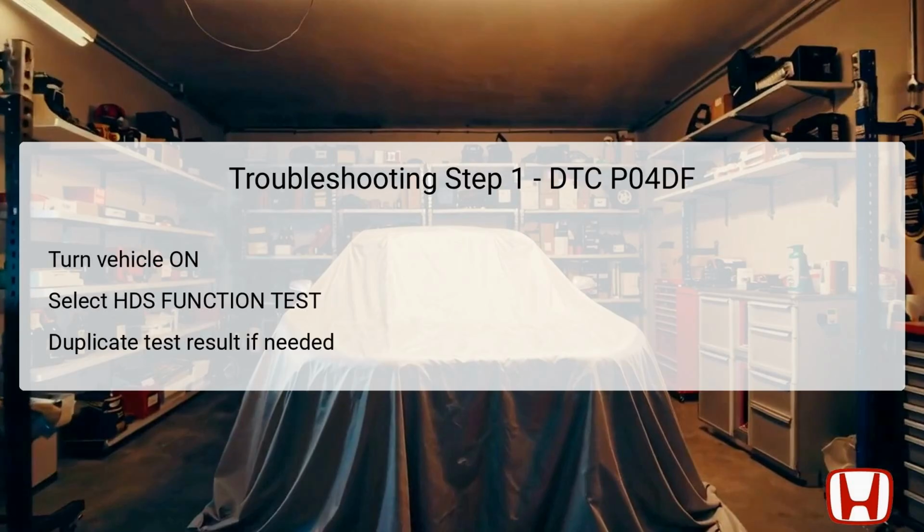The first step in troubleshooting the DTC P04DF involves turning the vehicle's ignition to the on position without starting the engine. This step is vital for powering the onboard diagnostic systems. Once the vehicle is in the on mode, the next action is to select the HDS, or Honda Diagnostic System, and navigate to the Function Test menu. The purpose of this is to perform a diagnostic test on the EVAP system functionality.